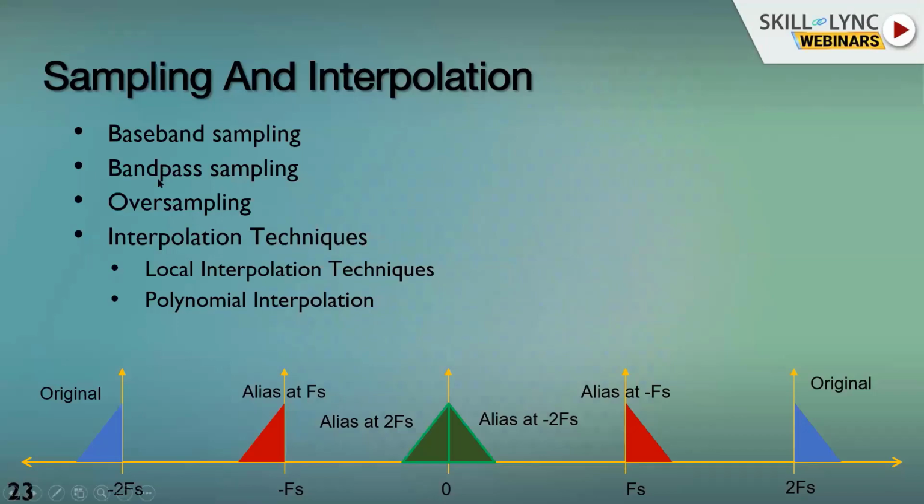So what we do is bandpass sampling, because even though the maximum frequency component is here, the signal is limited to this band of frequency only. So we can utilize bandpass sampling in this scenario, and instead of sampling at 4 fs, we can sample at only half of this frequency, I mean fs, and that will create images of this spectrum at this and this frequency and here, and then we can use a low pass filter to take out this spectrum, and then we will get our signal back.